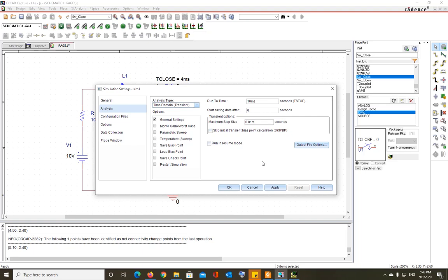That is the state at which they are moving between two constant values, and that's called a steady state value. So we run the simulation for a long amount of time, but then we only want to see the last few milliseconds or microseconds where it gets to the steady state. We are not interested in the whole simulation. So in those cases, you put the time, let's say, 9 milliseconds, so it's only going to show from 9 millisecond to 10 millisecond.